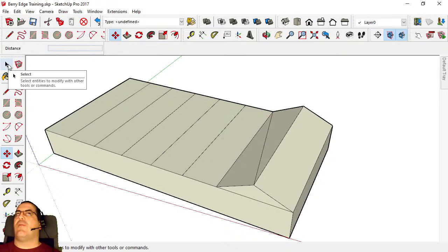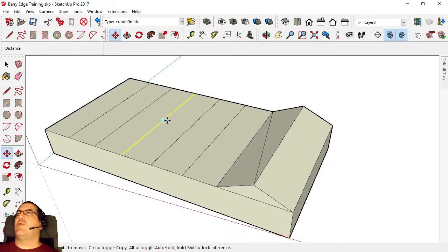If you're not sure if anything is selected or not, because you can't see it, but you're not able to select the thing that you want, select your select arrow and just click on any empty white space. Right, let's try that again. Go back to our move tool and you'll see that our auto select is working again now. So basically we had something round here that we couldn't see in our current camera view selected.